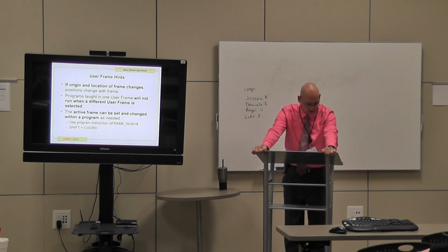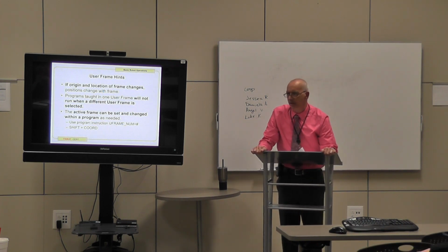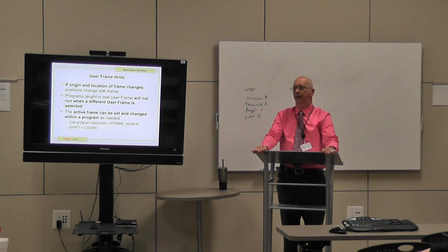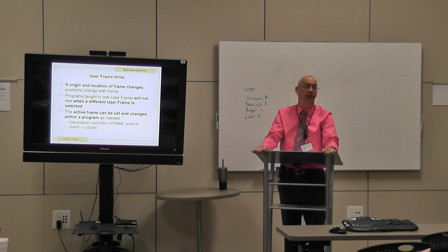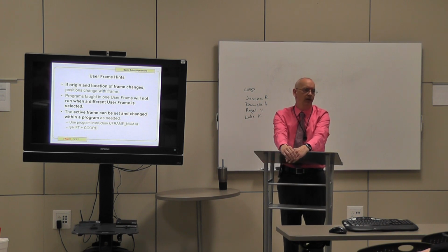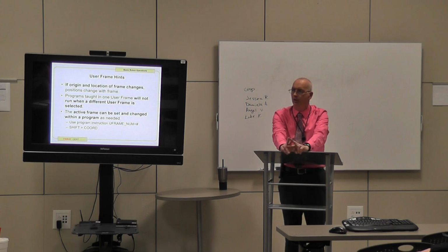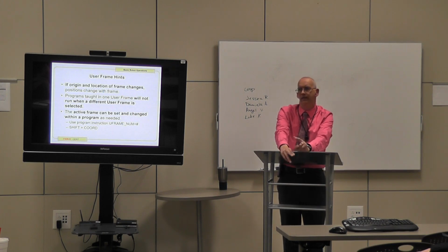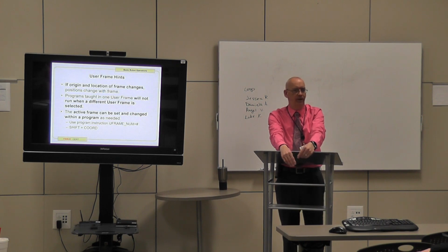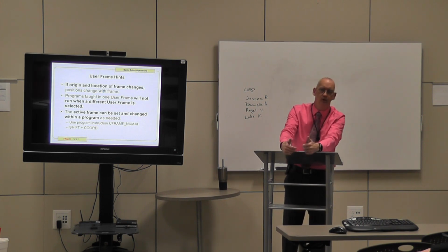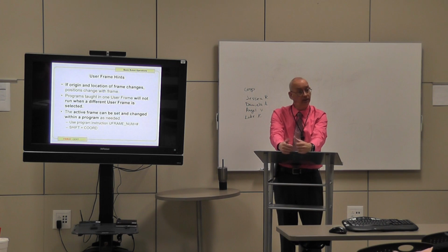Okay, another way you can do it is by manually inputting your user frame by hitting the Shift Coord key. When you hit the Shift Coord key, you are going to adjust your user frame and your tool frame to the assigned frame that you want to use in your particular program, while you are teaching or running it in manual.